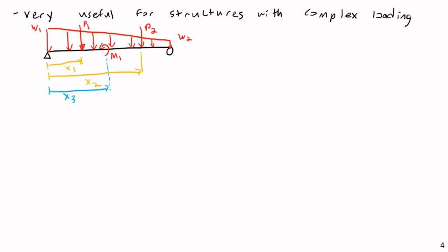If I wanted to find the deflection by integration, I would need to do this across 4 different zones using the boundary conditions from one into the next. It would be a royal pain, which we could do, and it wouldn't be so bad. But we do have another way of doing this. Because remember, we have said that as long as the responses are linear, we can simply sum up the inputs to produce the final output. So how do we do this?